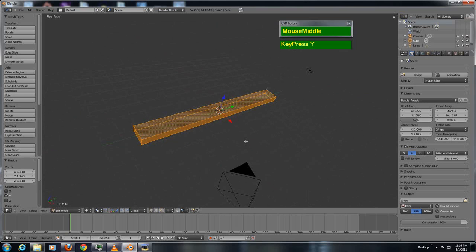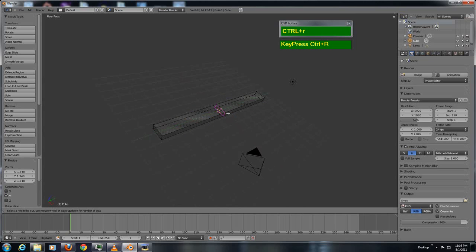Okay, next I want to introduce something called an edge loop. Let's just plant one edge loop first. When I press Control R, it will introduce an edge loop. When I move my cursor along the edge, you can specify which orientation you want the loop to run across. So in this case, when your cursor is near this loop section, the edge loop will run across this direction. If you move your cursor here, it's going to run along this direction. For an edge loop to work, you have to have four-sided adjacent faces for the edge loop to run across.